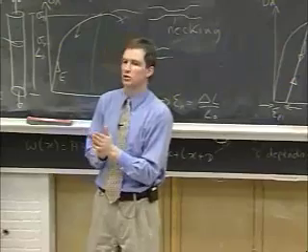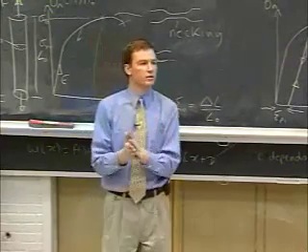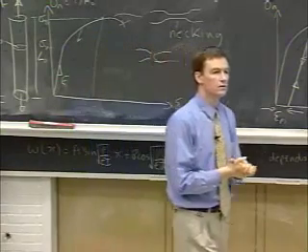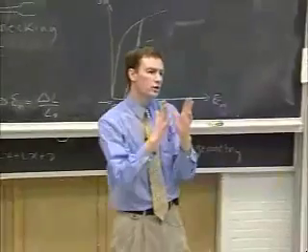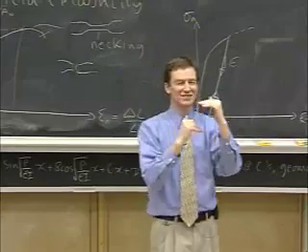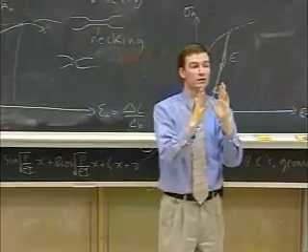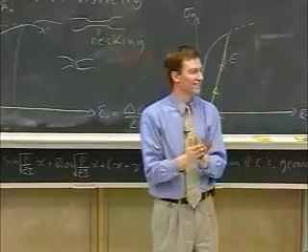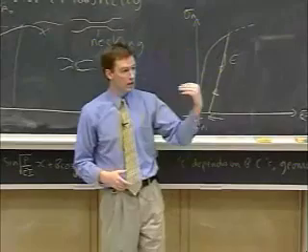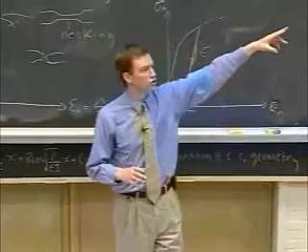What's one of the key limitations that our model for strain and displacement depends on? Jonathan? It's got to be a long beam. No, remember we defined strain displacement relations for this infinitesimal cube or square of material. Yes, so long as we're dealing with small deformations, less than 10%, ideally less than maybe a couple of percent strain. And what's the strain here?